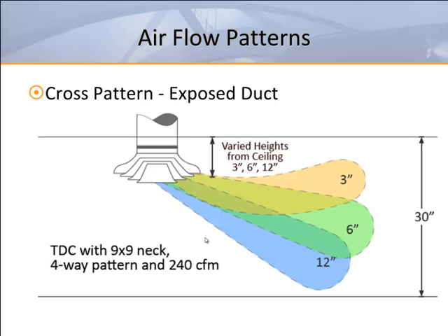When an outlet without an internal negative pressure pocket is mounted more than 12 inches below the ceiling, the air will discharge downward at an angle of approximately 30 degrees. This will not adversely affect the comfort in the occupied zone if the 50 foot per minute terminal velocity remains more than 6 feet above the floor.